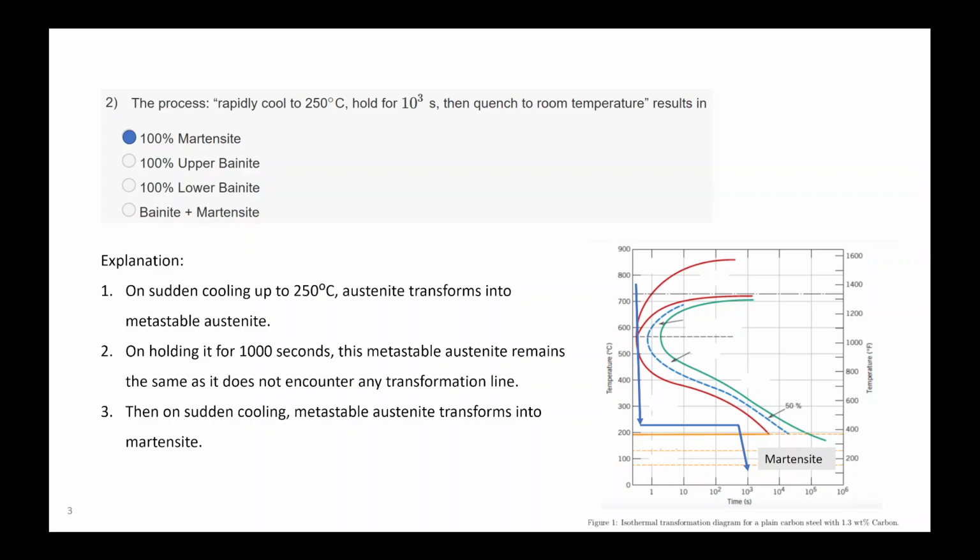Smooth contour means, in the case of a material which doesn't have any fillet versus one that has a fillet, compared to a square corner you would prefer rounded fillet-type corners. But if you have a smooth contour that you are forming, then it will have less stress concentration. If smooth contour is also present, then I think that should be the answer compared to fillet.